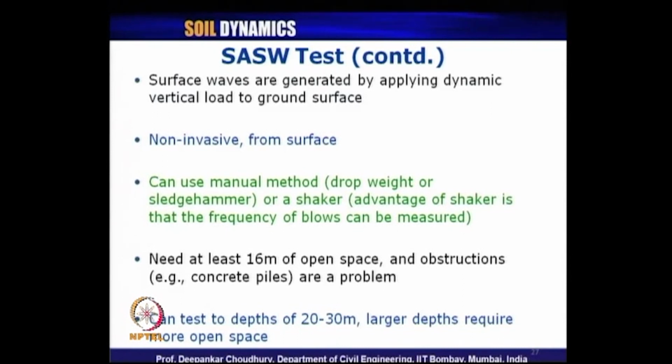Otherwise, what will happen? The waves will not get sufficient distance to travel to generate both surface waves and other body waves. So, you cannot differentiate the time of arrival and so on. So, we need at least 16 meters of open space.